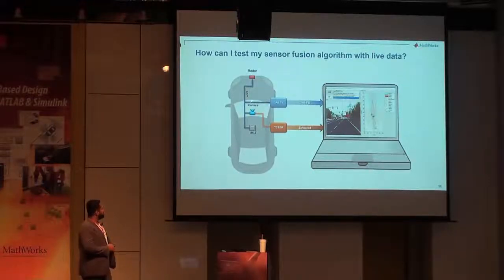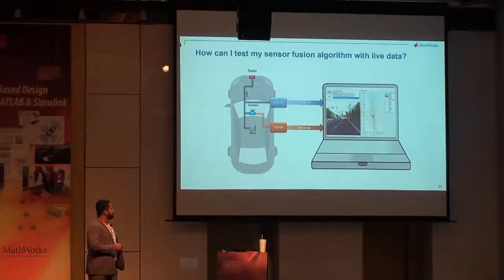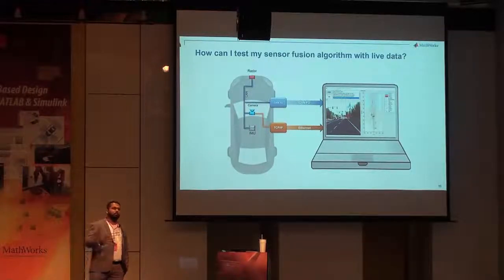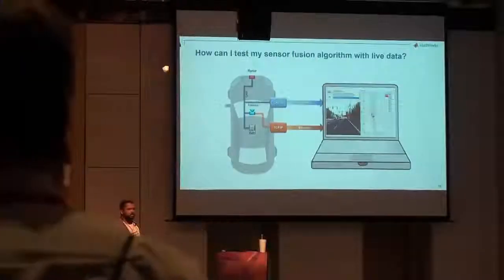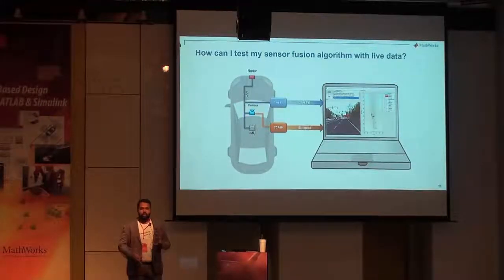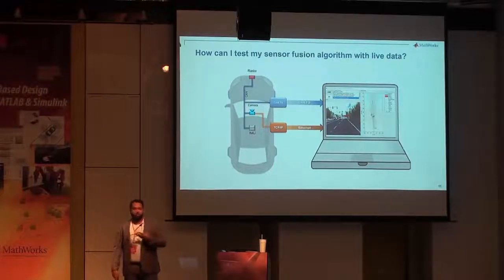For example, you may have radar sensors that are communicating through the CAN bus. You may have IMU sensors. You may also have camera sensors that are capturing over the Ethernet. So whatever configuration you have, you can connect to that in MATLAB and bring in the live data, which is useful, and we'll see for the following example.